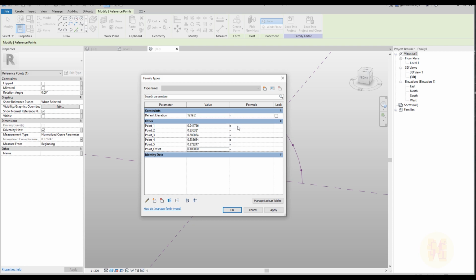We should now say we know the 1, it's the static number, 1 means 100% closed shelter. We want to do minus point offset. Let me write point, it's much better like that. Be careful with the naming, because if you get it wrong, Revit will not use it. As you can see, from the 100% we subtract the 10%, and here it's going to be 0.9.